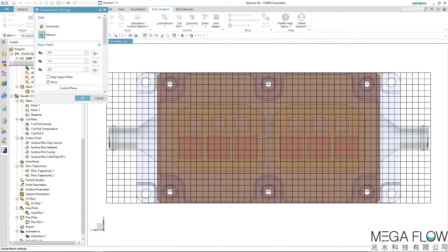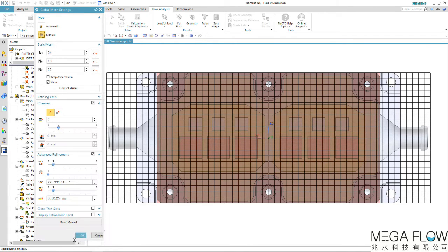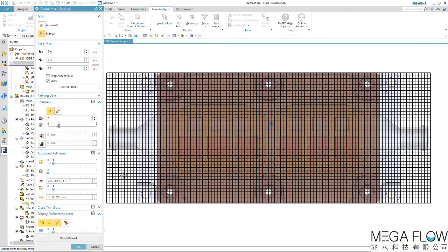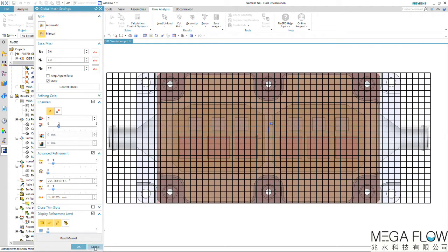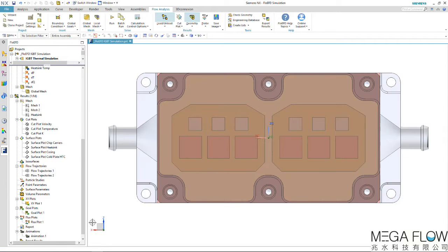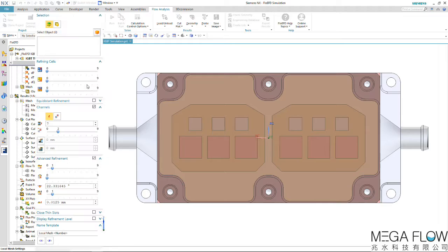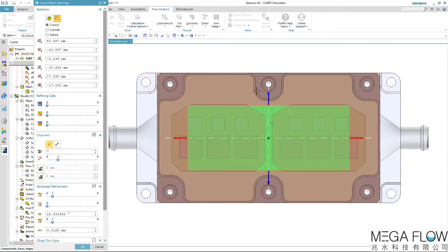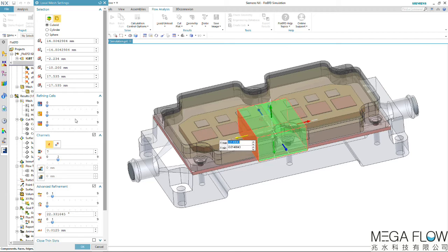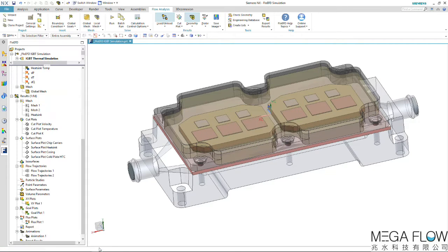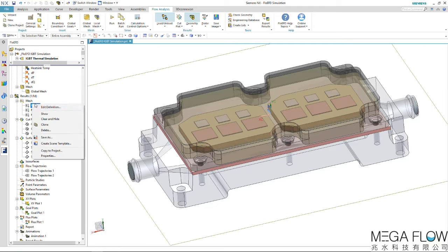The mesh on the screen is only the base mesh before any cell subdivision has occurred and is visualized to give the user a rough idea of how fine the final generated mesh will be. The mesher can be switched over to manual settings if desired, where cell sizes and refinement settings can be accessed. User-defined local initial meshes can be employed to manually apply finer grid on specific parts and areas in the model. The mesh has already been generated for this model, so now let's have a look.